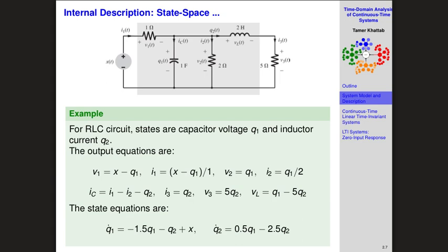Yes? We take only capacitor and resistor and load as variables. We take only what, sorry? Capacitor and the load as variables. We don't take resistors. Yeah. Resistors are simple elements, I described this earlier, right? Resistors are elements that cause only a multiplication by a constant, so they do not affect the order of the system. Capacitors and inductors do differentiation and integration, so they affect the order of the system.